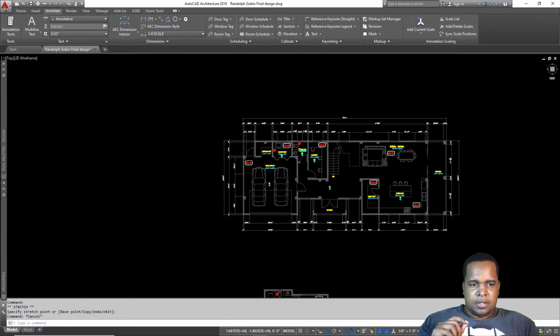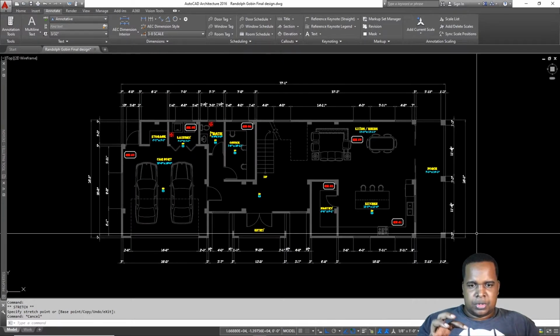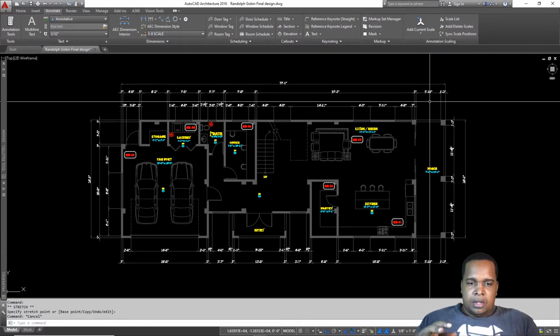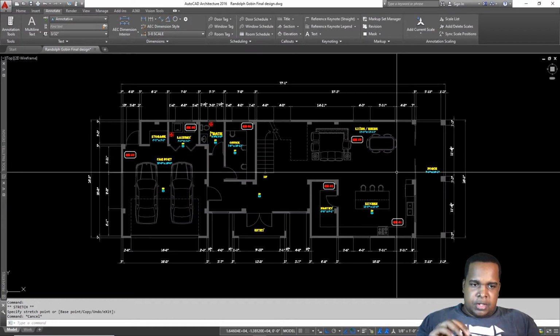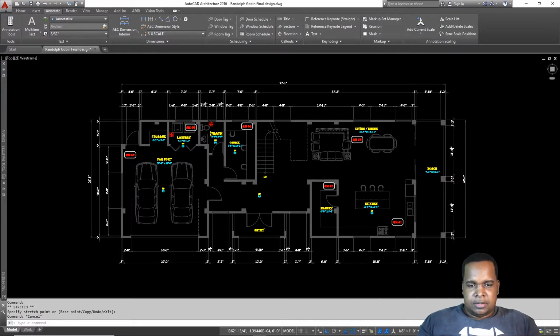Right? What I'll do next is I'll show you how to dimension the inside. Alright, so when dimensioning the inside, we need to be aware of where you're pulling the dimension lines from. For example, you don't want one dimension crossing in front of the next and making it complicated to read. So it's not really a hard process. Just take some time and look at where things fall.